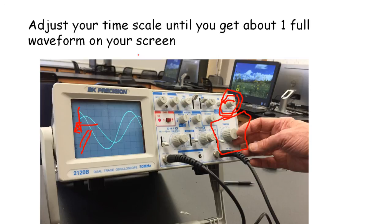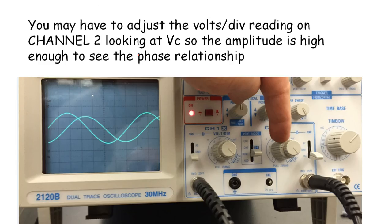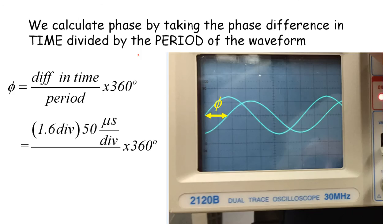So it perfectly intersects one of your grid lines, and then it's easier to measure this distance. That's handy, you'll use that. You may have to adjust the volts per division. Just like we did in Multisim, the voltage on the capacitor is going to change at different frequencies, so you might have to boost that up or lower it down to make it fit right.